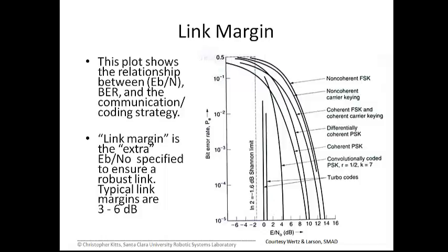And if I move all the way over to the non-coherent frequency shift key curve all the way to the right, and if I roughly move down, that wasn't perfectly vertical, but I'm kind of in the area where I need, say, let's just call it 10 dB of signal to noise in order to make that work.